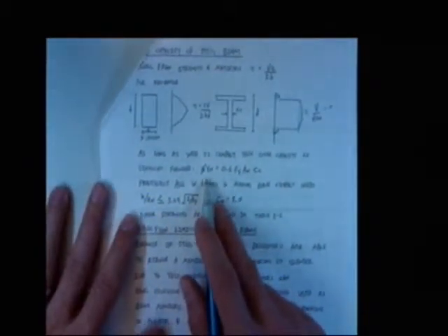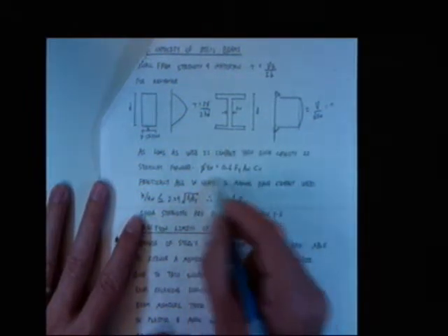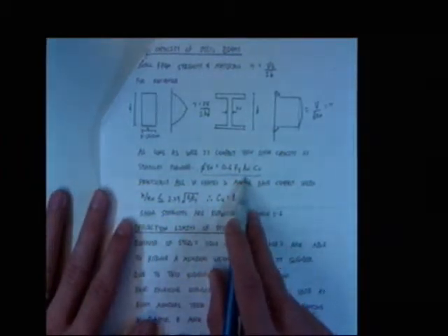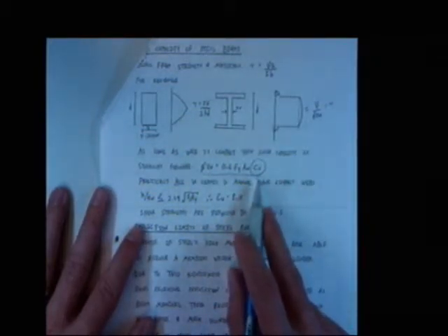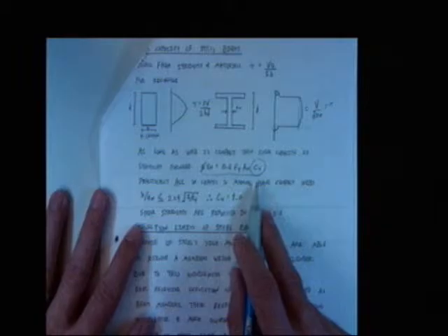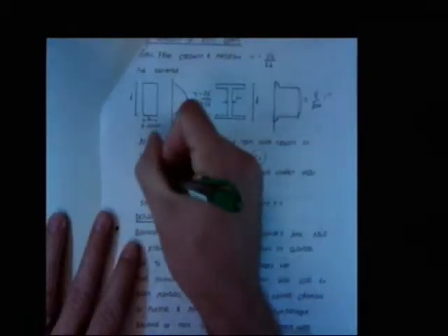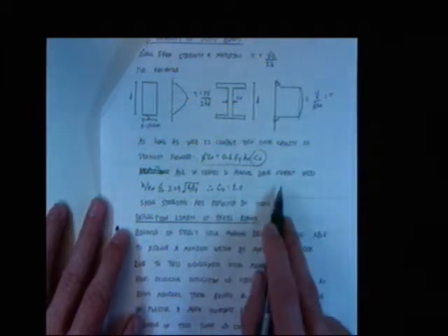So this is what they end up using inside the steel manual for I-shaped sections, an equation that looks something like this. And this equation is going to come back later on. This C sub V. Does everyone see this C sub V? The C sub V is going to come back and haunt us later on. You're going to hate this value later on. Okay? We're fortunate right now, though, because I say practically, and you can just mark out the word practically, all rolled sections, all W shapes in the manual, all rolled sections have compact webs.